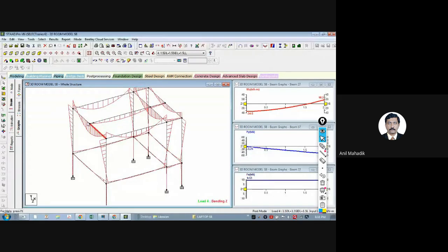See, it is assuming that it is one beam only. So there is no problem, even though it is split in two parts. But there is an issue with the STAAD Pro software: whenever you support any secondary beam on the primary beam, the primary beam gets split into parts. There is no problem regarding the behavior, but you need to click each and every part.